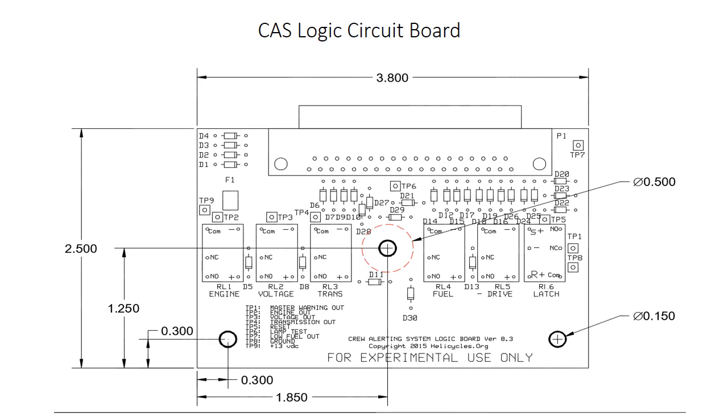So if you're using a socket or some other tool, as long as it doesn't extend outside of that little dashed circle, you're not going to damage the board. There are no components within that 1/2 inch diameter clear area for the center. All of the inputs and outputs come through the top to a 37-pin D sub-miniature connector.